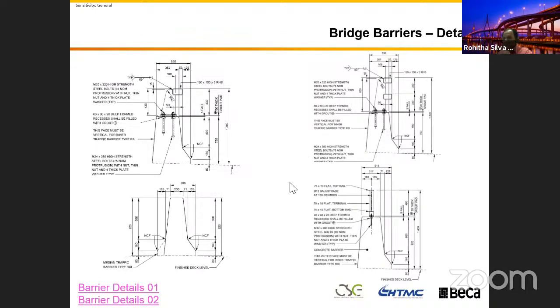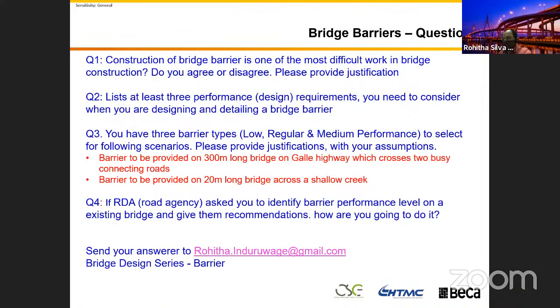In addition to that, in the bridge, because we said people walk next to the barrier, when you have a shared path or cycleway, normally for safety reasons, we have a cycleway railing in Australia about 1.4 meters above the riding surface. We add the railing and we combine those together and we design the barrier. Yeah, I'm not going to go into detail on this stuff.